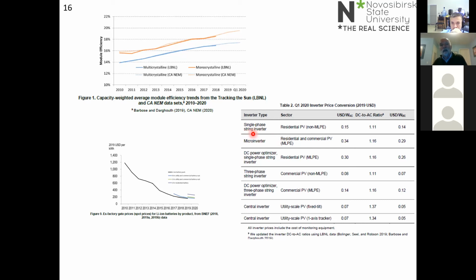And in the context of photovoltaics, a string means a small number of PV modules usually connected in series. So a string may contain 5 PV modules. If you have a rooftop system on your house, then that is probably a string of 5 or 10 PV modules. You can have one inverter for that string of modules.